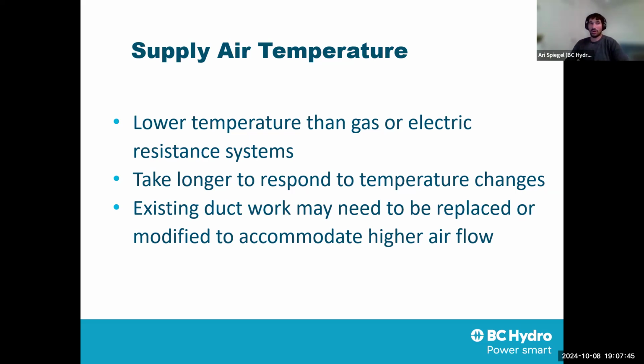It's also not going to feel as hot to you. If you're sitting by a duct, by a vent, and you're feeling that air, 26, 27 doesn't actually feel like it's warm. So a lot of people are like, oh, my heat pump's broken, it's not feeling hot. But no, we're used to temperatures of 40 plus, or if you're on electric baseboard, very warm, radiant heat coming off of a unit. So a lot of complaints stem from, I don't think my heat pump's working, it doesn't feel hot, but that's just the nature of how it works.